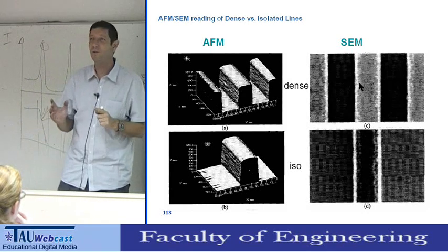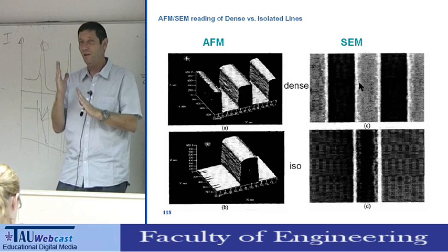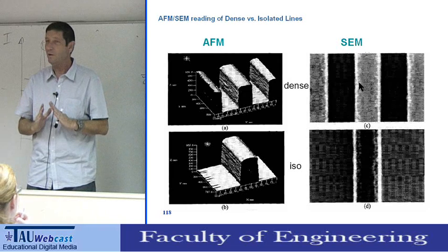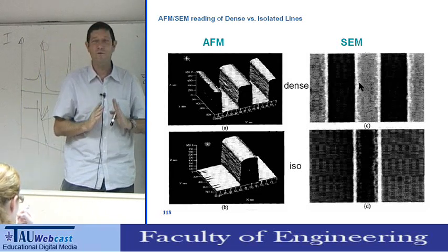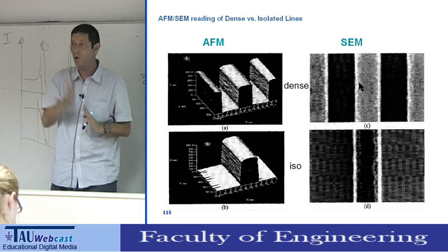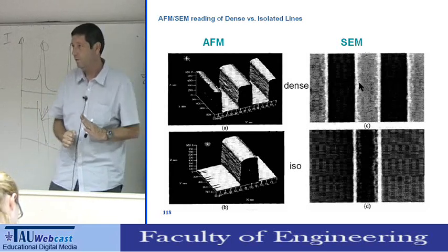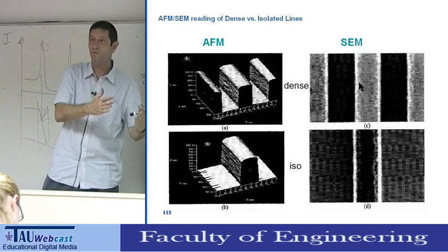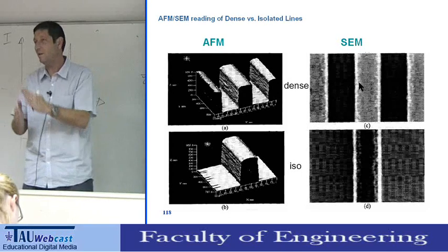Because if the error is random, I have a problem. But if it's a fixed shift in the value, I can calibrate it. It's a strong function of the slope of the line, but I can calibrate it because for every slope, it's a fixed value. So if I can estimate the slope and I have the AFM values, I can correct the SEM values.